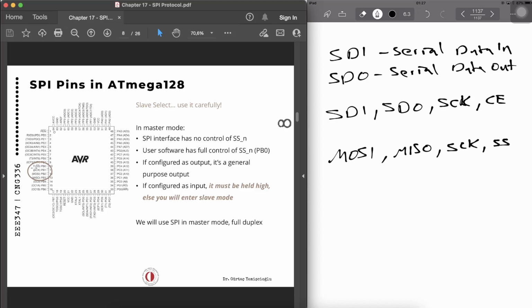Another important thing: the SPI protocol uses the clock to synchronize the transfer of information 1 bit at a time, where the MSB goes in first. During the transfer, the chip enable must stay high. The information, like the address and the data, is transferred between the microcontroller and the SPI device in groups of 8 bits, where the address byte is followed immediately by the data byte.